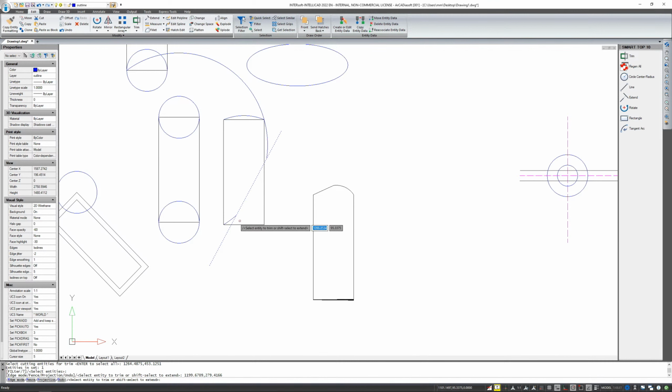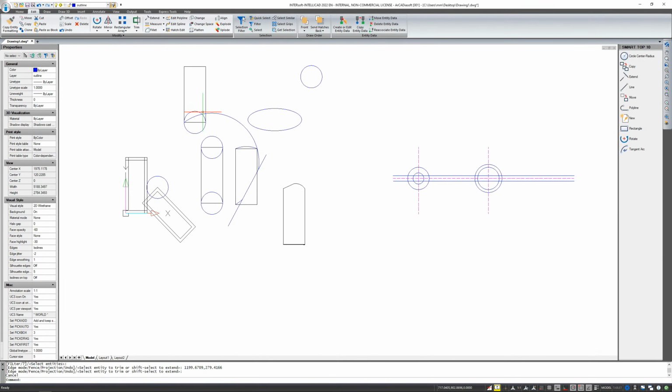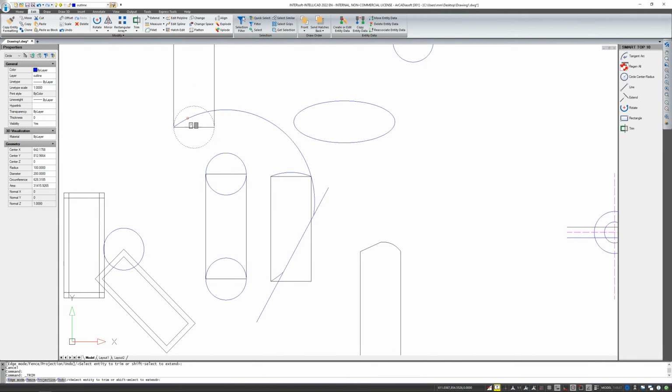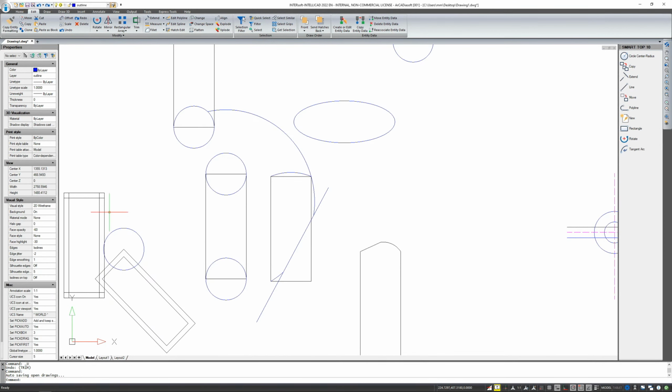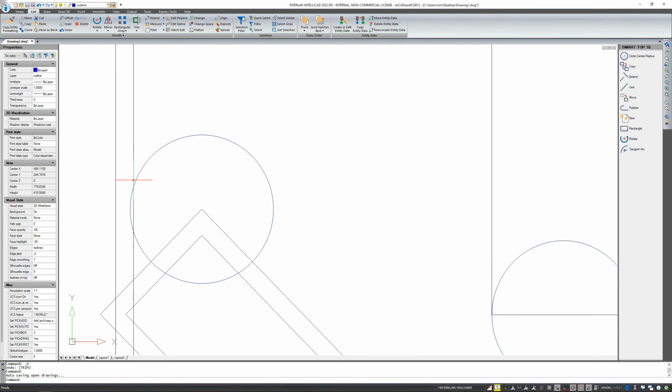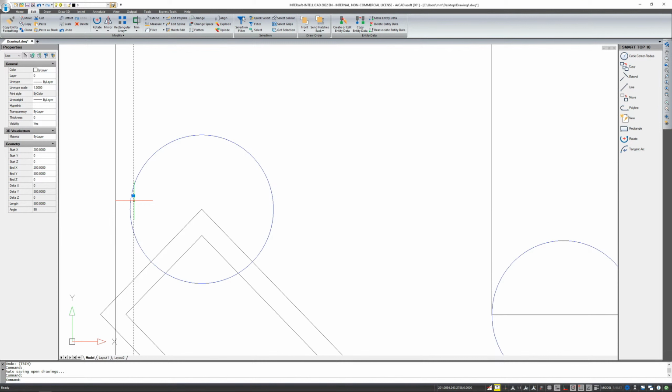If I still want to get rid of the two pieces that are now marked, I just have to remove them. And in a similar way, I can remove these two lines from the second circle, from here. And now also remember that when you're selecting the circle and what should be cut, indicate it, click at the end with the right mouse button or Enter and exit the option. When it comes to cutting in this area, it is quite important what you choose to cut out. Please pay attention. If I want to cut this piece of the circle, I mark this line because it will cut this circle. I confirm it with Enter and show that it is not there.